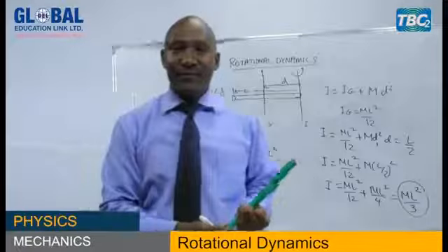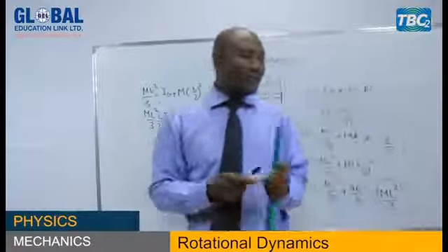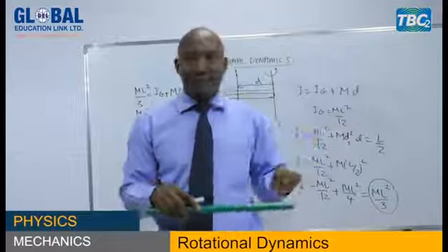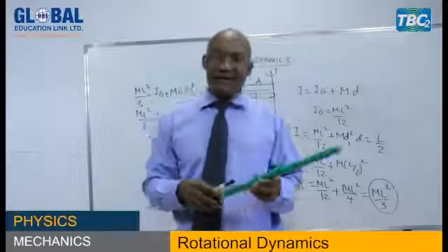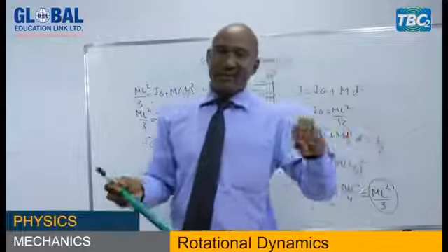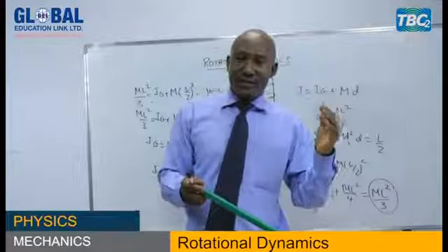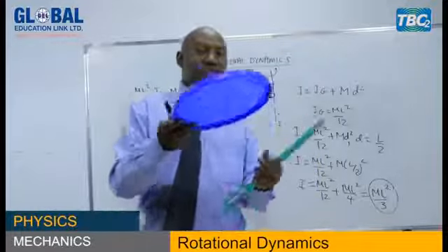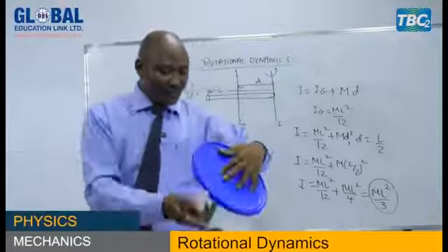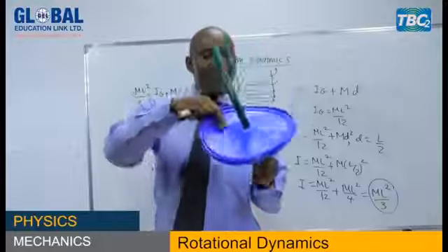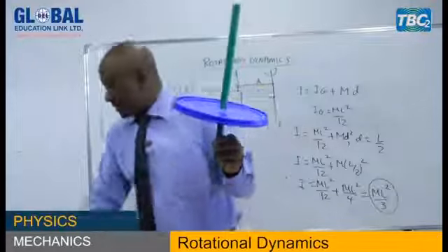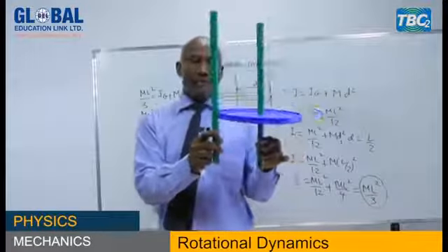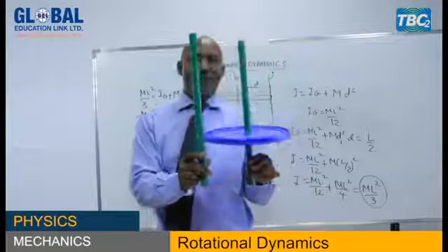So it's very simple. As long as you know how to apply this theorem, you will enjoy it. This is one particular explanation. We can have different figures, not only this one: circular disk, sphere, ring. The principle is the same. Mind you, when you talk about the circular disk, as an example number 2, we have the moment of inertia about the center. We know it. We might be looking for the moment of inertia about another axis, which is passing through its circumference, like this, but parallel. So the formula is the same.